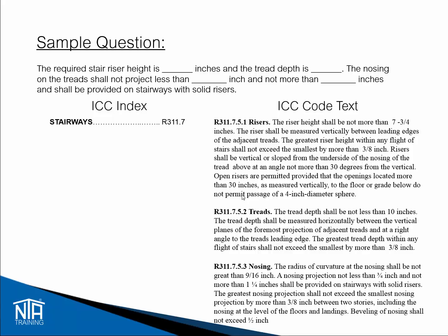In this question, you are looking for the dimensions of stairs, including the required riser height, tread depth, and nosing measurement. Start by searching the index for stairs. The closest you will find is stairway, which directs you to section R311.7. This section starts by giving the width and headroom required for stairs, but you are also looking for riser and